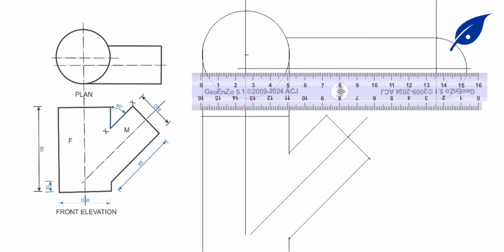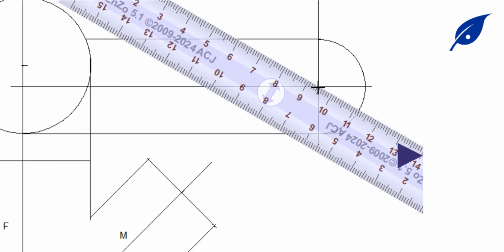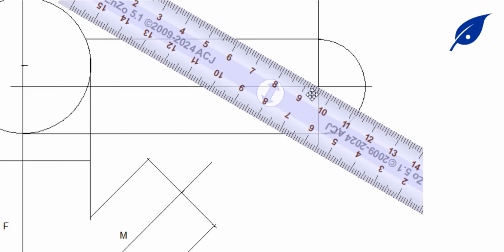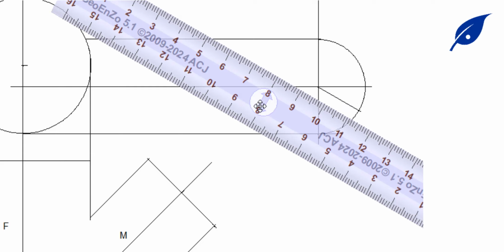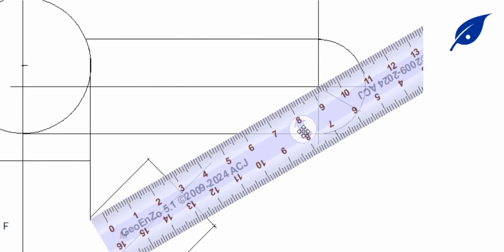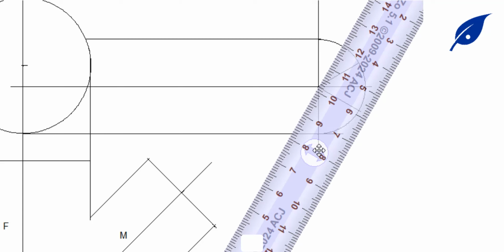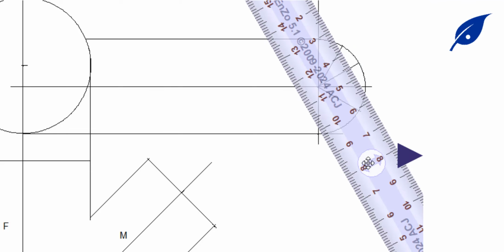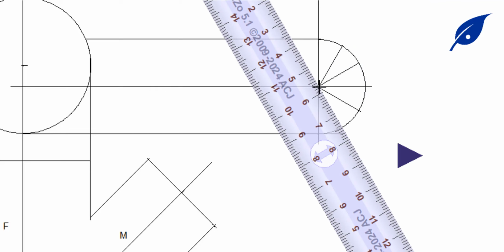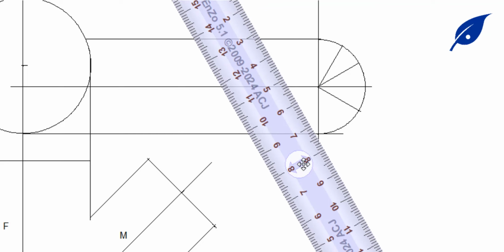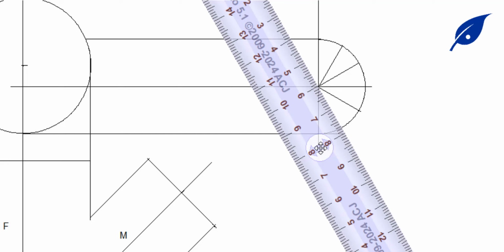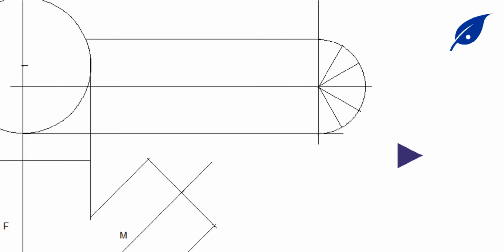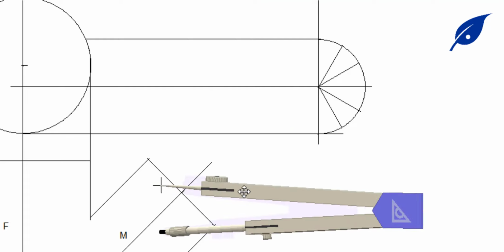So we're going to draw it this way. After having this outline for the plan, at this point, we'll divide the semicircle into 6 equal parts using the 30 degrees and 60 degrees set square to divide it, which will give us the required angle at this point. So after dividing it, we'll label it 0, 1, 2, 3, so that we'll get the required view.